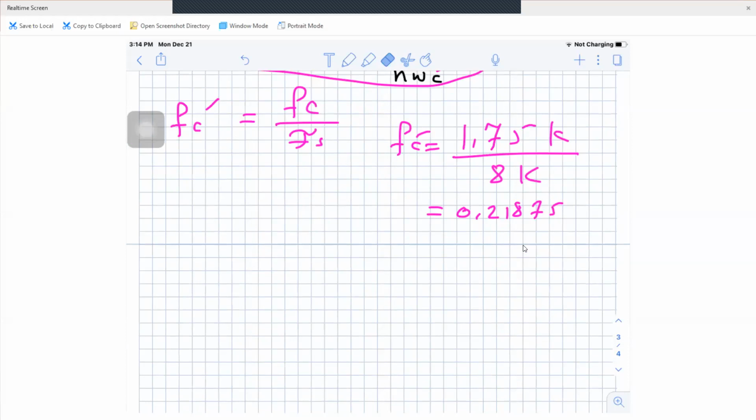Well, now, what about the window function? We said that based on the stop band attenuation, which must be greater than 50 dB, going back to the table of windows, the Hamming window will satisfy the condition of the desired filter. Now, the equation of the Hamming window will be as follows.